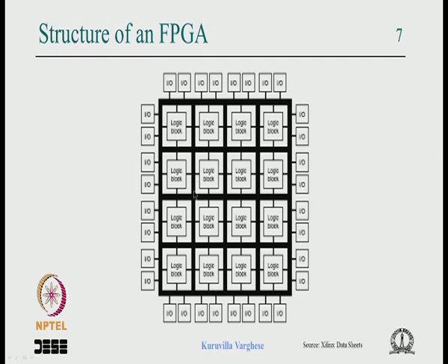So when the tool puts some hardware into the FPGA, it will be placed across multiple logic blocks, and depending on the circuit synthesized, that will be interconnected using these general wires. There are wires which span a single logic block, wires which span maybe 2 logic blocks, 4 logic blocks, 6, and from one end to the other. Now these come from the statistics.